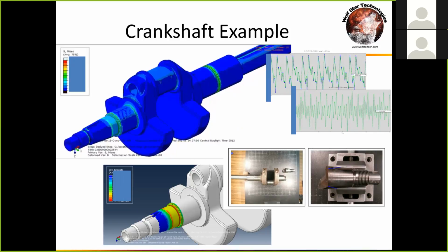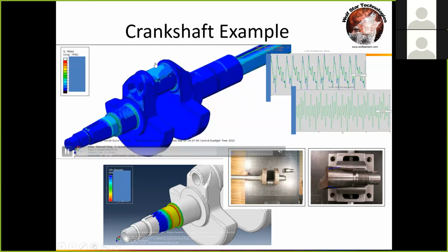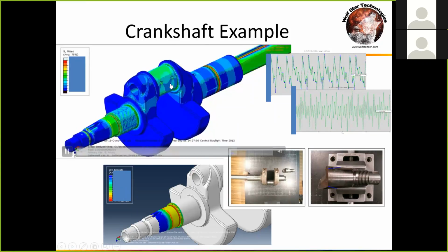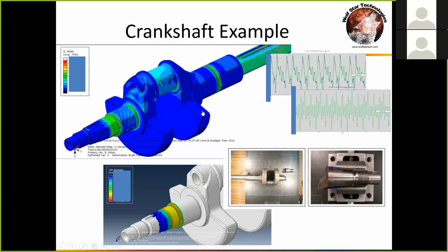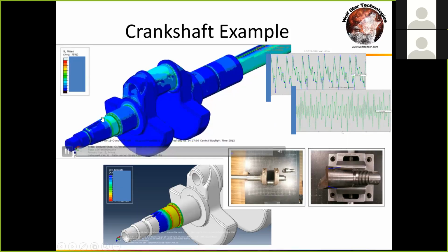And I didn't know much about engines, but we worked together, and working with the engineers, we came up with unit loads in the crank pins, so X and Y loads on the crank pin, and then they said that there's some modal content here. So we had a torsional mode and 2 bending modes of the flywheel on here.